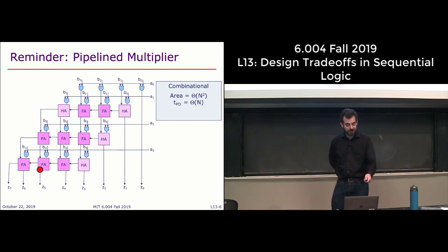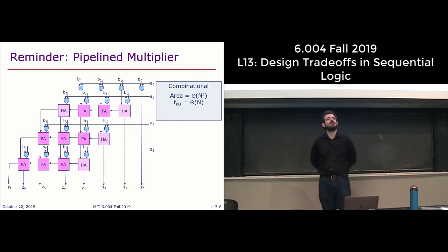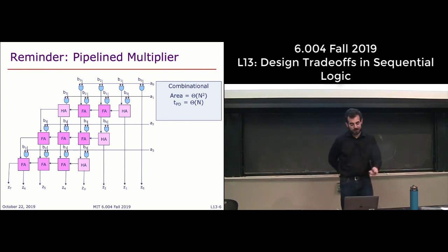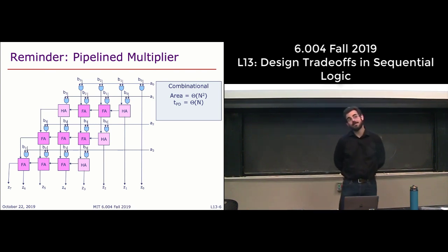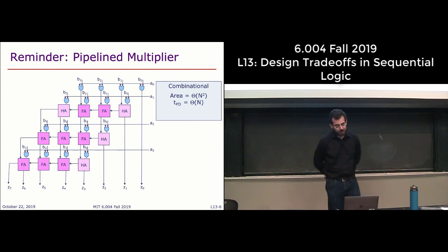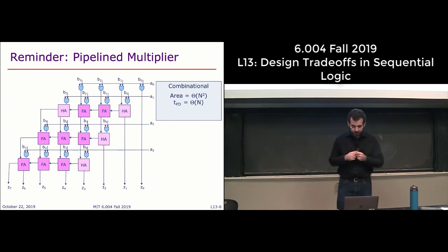So you're going to do this step. If you imagine that I had n bits here, we do n minus 2 of those, and then times 2 blocks that we cross, right? So in that case, the general formula for how many delays you have is n plus 2 times n minus 2, so 3n minus 4. And 3n minus 4 for 4 bits happens to be 8, which, yes, matches what we have here. But forgetting about the constant factors, this is order n, right? This is an order n delay.